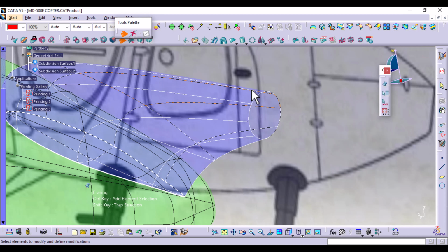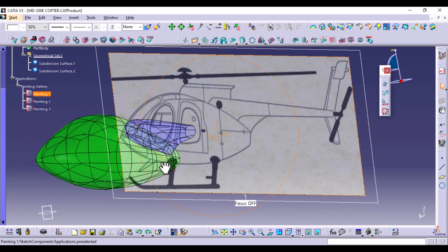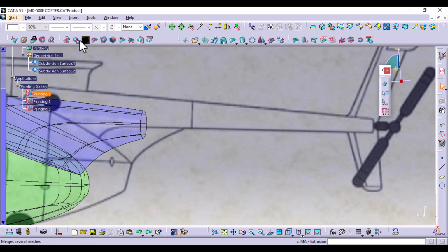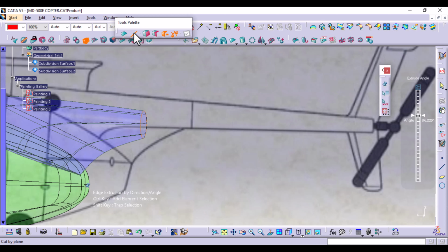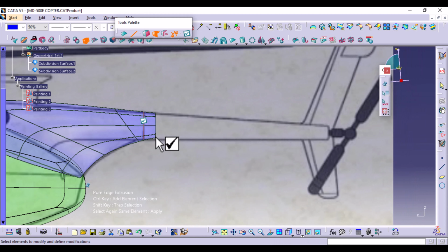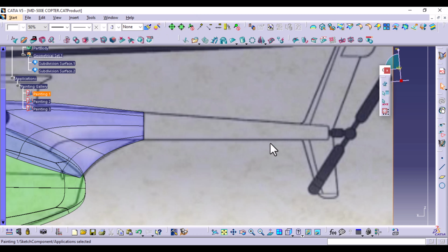Now we have an open edge. And you have an option to just pick the edge and extrude it. Like you can come here, select extrusion, select the subdivision surface, make sure it's the edge selected, and select extrusion here. Select this edge, and it's going to give you a new surface. And you can click yes on that and then extrude again and pull it out. But you're going to have 3 junctions here, but I want to have just 1 junction, so I need to be able to control that. So what I'm going to do, just exit this and don't save.